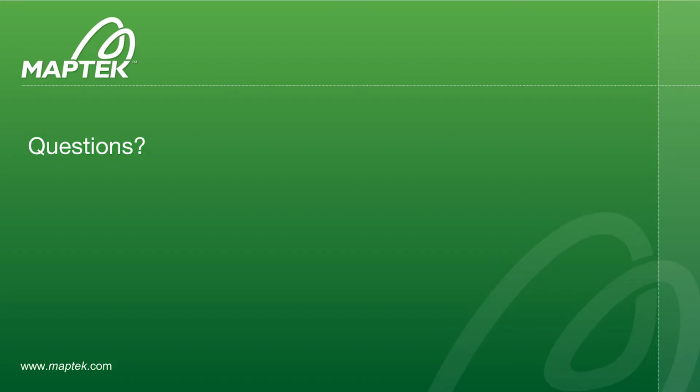Thanks so much, Roxana, for running through BlastLogic electronic tie-up tools. We have got a question for you. If the shot firer has placed an additional primer into a hole, how can I change my timing plan to account for it? Okay, so we actually have an option called Edit Primers in BlastLogic.